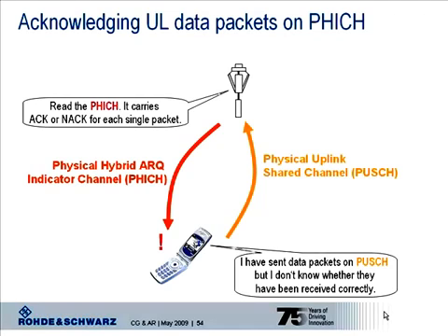We already ran into this channel as we discussed the information transmitted via the master information block. The master information block carries duration information for the PHICH. The duration of the PHICH differs for LTE FDD and TD-LTE. The PHICH is always transmitted in the first symbol of each subframe in the downlink. The ACK/NACK information on the PHICH corresponds to the data packet sent in the uplink 4 milliseconds before.